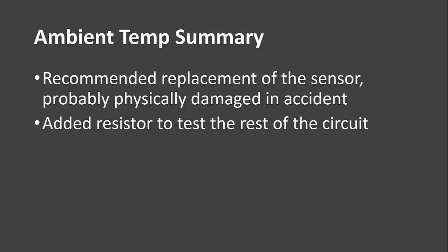Other times that it's helpful to add a resistor to a temp sensor circuit is if you need to, say, get a monitor to run. It's a 0-degree day and you've got some monitors you need to run. You may have to trick the intake air temp or ambient air temp sensor circuit into thinking it's a little bit warmer outside in order to meet the enable criteria.